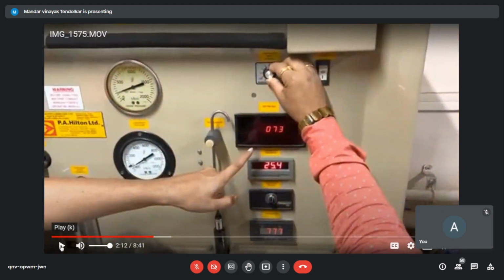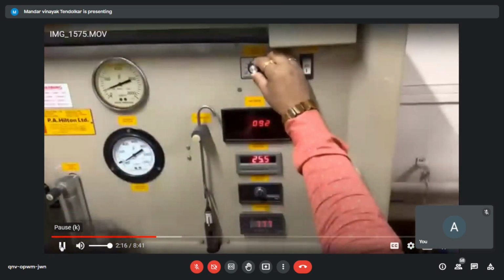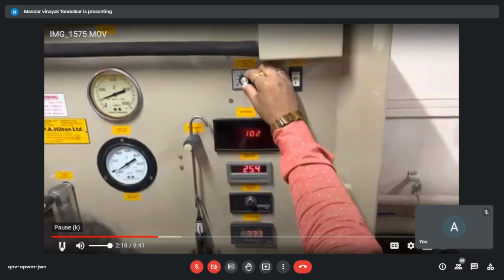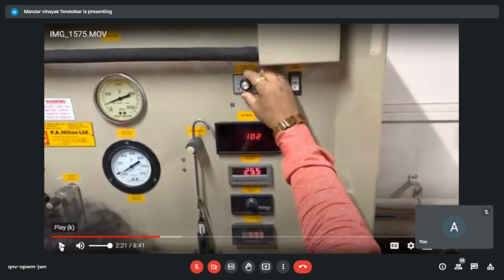See here you can see he is giving the evaporator input. So this is now, it was 5 watts earlier, now it has become 73 watts. Can you see this? DC. 75, 80, 90, 97, 100. Okay, so we finalized around 100 watt as the evaporator load.